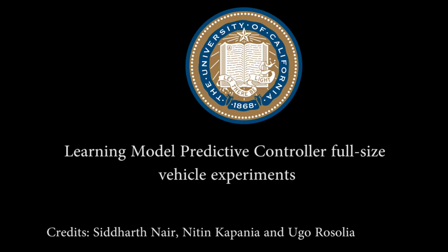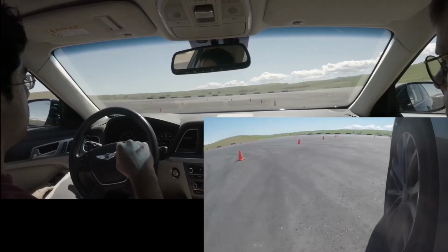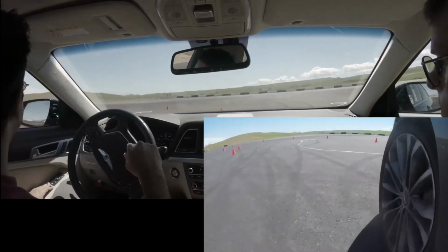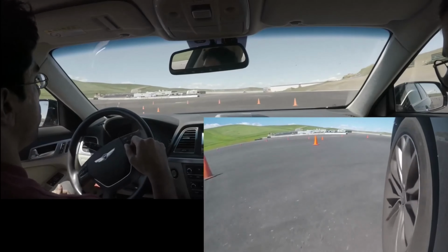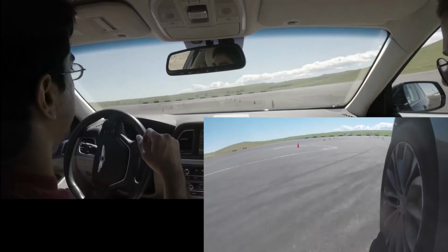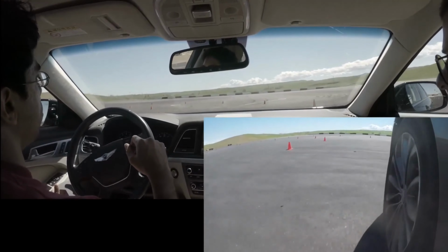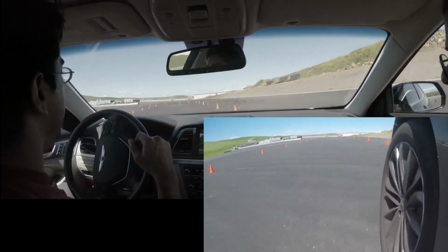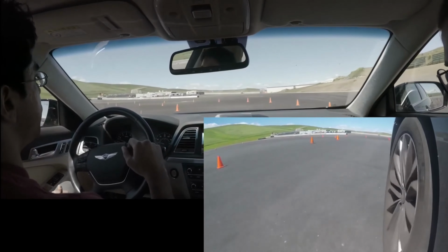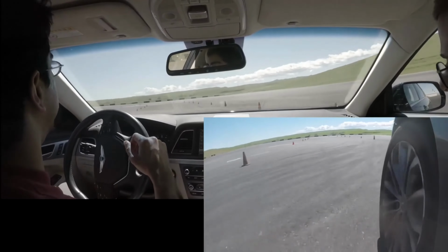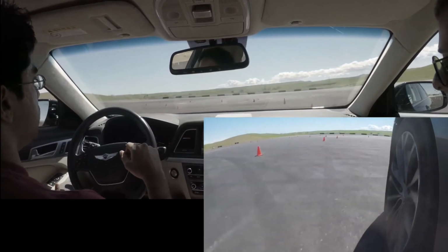And you can see that when they apply this idea to a full-size car here on a racetrack, in the beginning this car is driving very slowly and conservatively because it doesn't have a good idea of the cost to go, so the cost beyond the prediction horizon. But after driving a couple of laps on this track, it has gathered experience and is able to compress that into this cost-to-go term, and they are able to even reach the friction limits of the tires in this example.